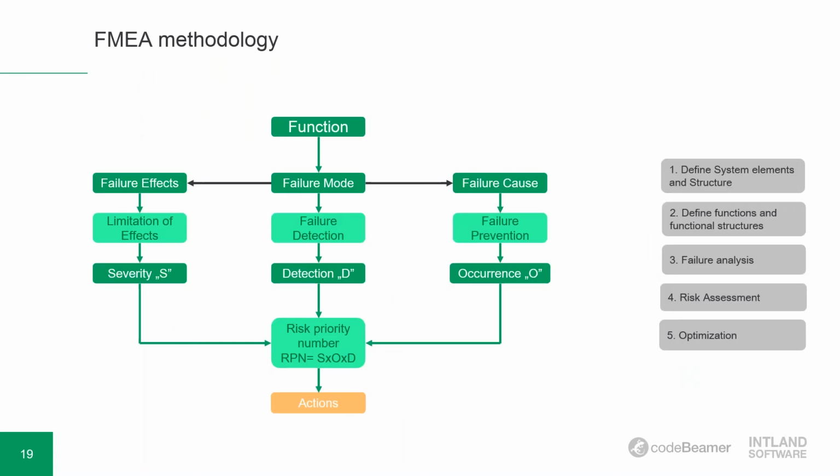And on any level I'm performing the FMEA, I will use the same guide words and try to define a proper functional deviation, so basically the failure modes. Of course, if I have experience from previous projects, I can use that experience, and I can use some checklists if I have them, and an overall strategy for the failure mode evaluation.